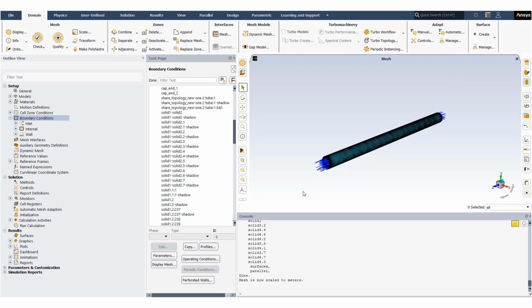We have some applications with very large models with hundreds of thousands of edges and faces to be shared. If we wanted to do all of this sharing topology only in SpaceClaim, it took days, but we verified this workflow, where we can do the share topology, create the conformal mesh and the volume meshing, everything together. It is just a matter of hours.